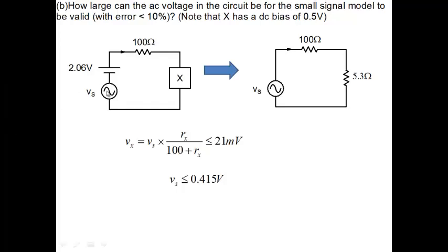We have to take out Vs first and do the analysis first without Vs, which is what we have been doing by approximating X by a linear element and all that. So do the analysis without the element Vs here. Find out what the currents are, the bias current. You will also get the net voltage across this element X.